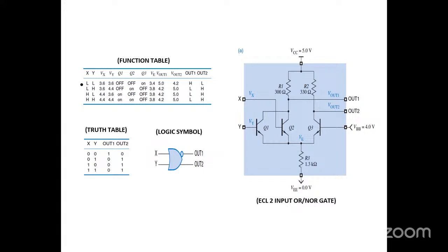output will be given, so the transistor will be on state, so that Q3 will be on because sufficient base emitter voltage is supplied to the base of the Q3, then it will be on, then output voltage will be plus 5 volts that we can get.